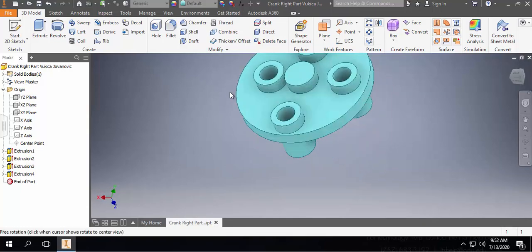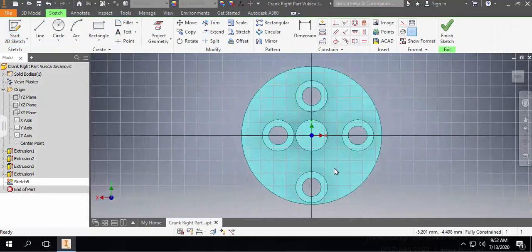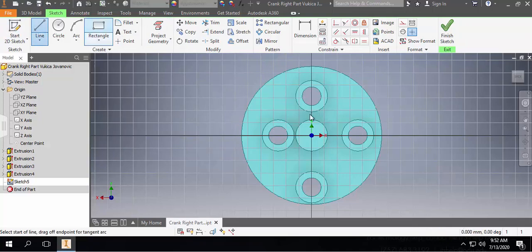You see where my shortest distance is, a little bit to the right, to the left. And I'm creating a hexagon cut feature on the back side, flat to flat distance 2.5 millimeters and 4 millimeters. So I'm saying here, okay, let's do it like this. And I'm going to make my hexagon there. But before I start, I again want to do my line. And my line will be construction line. So you see, I'm making it construction. And my X is there, so I want to say that that's a horizontal line.